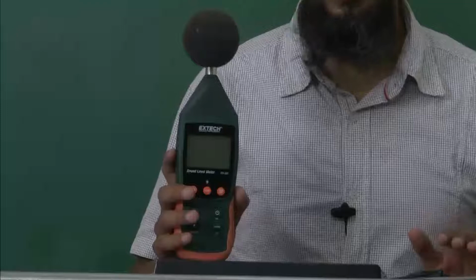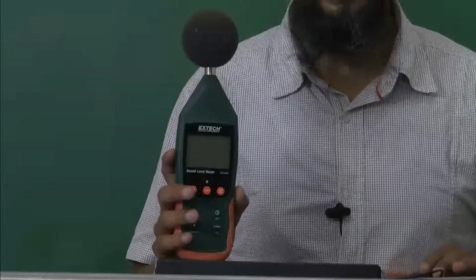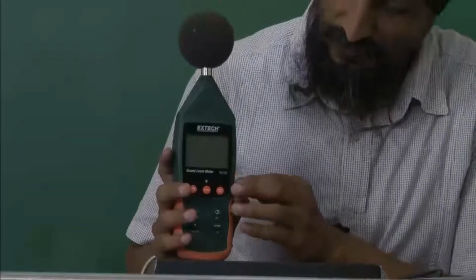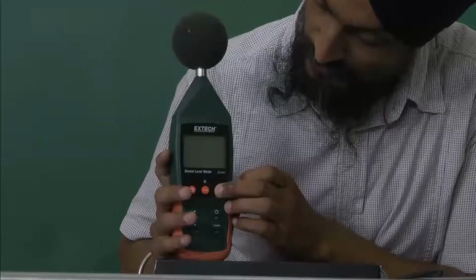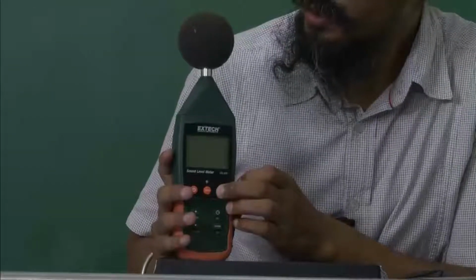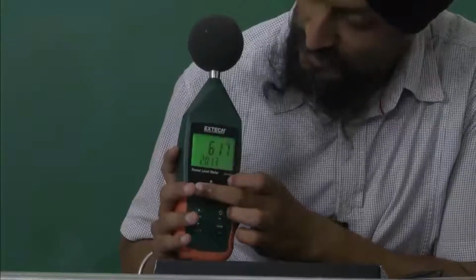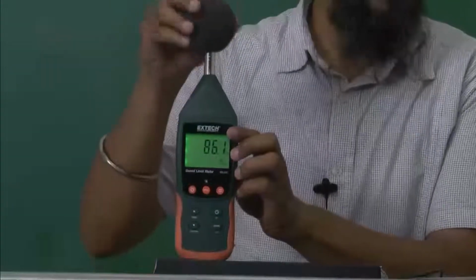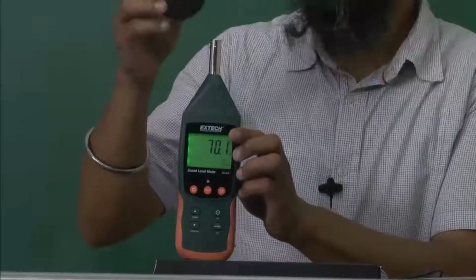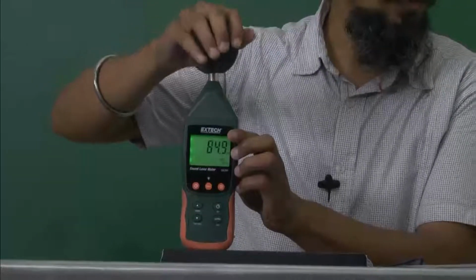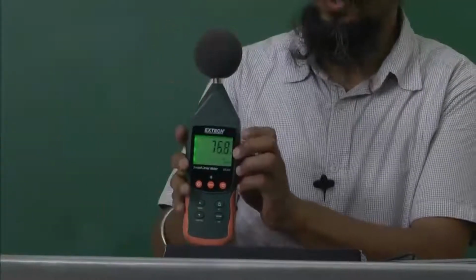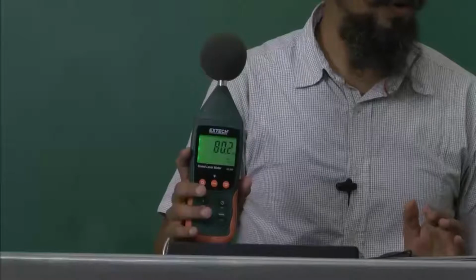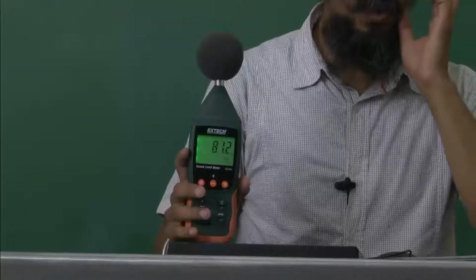So next I would like to tell you something about the sound meter, which we have used to record the sound while doing machining. So this we have here is the X-Tech sound meter. This is SDL 600. So to switch it on, I have to press the power button for 1.5 seconds and it switches on. So in this case, we have this wind screen, because wind blowing across the microphone increases the noise measurement.